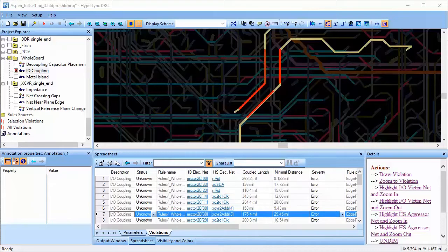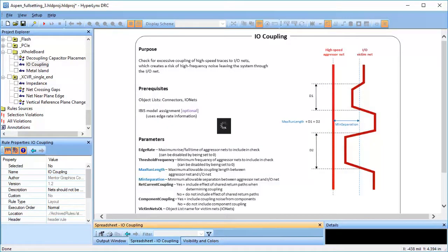We can investigate the effects of these violations further in the simulation, or the layout engineer can increase the spacing between the nets and take precautionary measures such as adding guard bands, etc. This way, HyperLynx DRC catches EMI issues that might have not been caught otherwise.